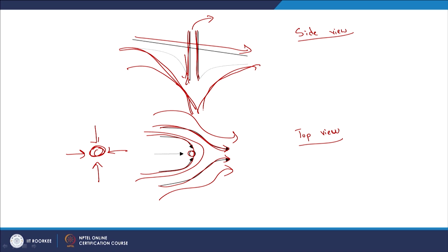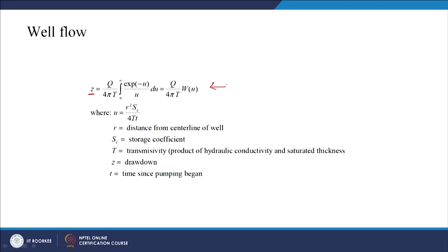So, obviously there are thresholds to this particular drawdown, as in if it is a confined aquifer, or depending upon groundwater regulations in that area, you do not want to affect the groundwater movement such that other people will be affected. So, you are going to have to consider those aspects and take that into account. To do that, I need to estimate the drawdown, and for that I have a particular set of calculations. So, let us look at that.